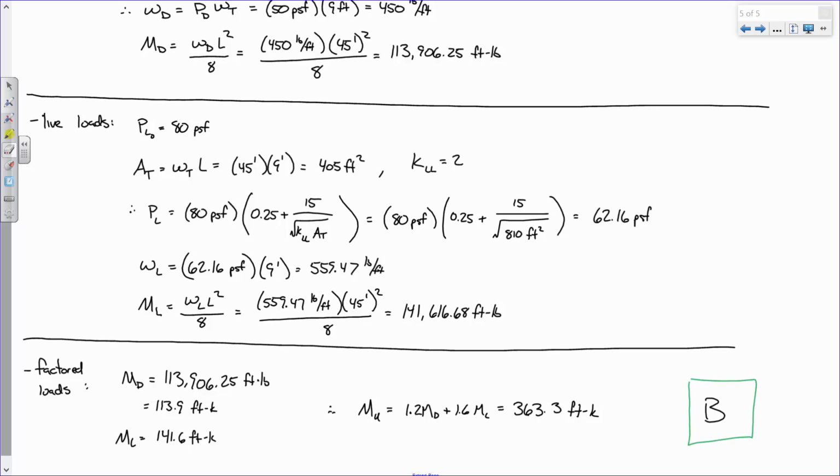It's a great question. The question was, when you have live load reduction, when do you account for single floors versus multiple floors? And the simple answer is this. Beams only support single floors. Columns tend to support multiple floors. So that's a simple answer for the exam. It's not always the case, but for the exam's purposes, that's pretty simple. I think we use the multiple floor equation. The multiple floor equation has KLL and AT and 40%, but this single has 50% and KU. That's a typo.